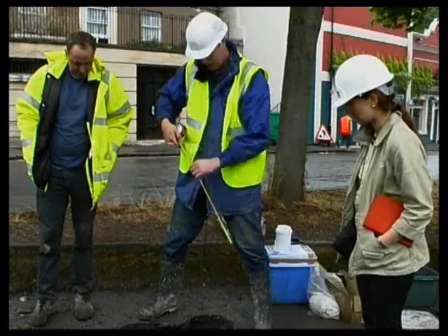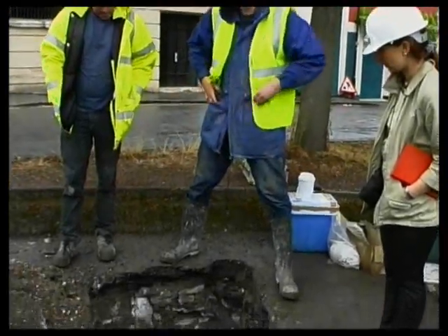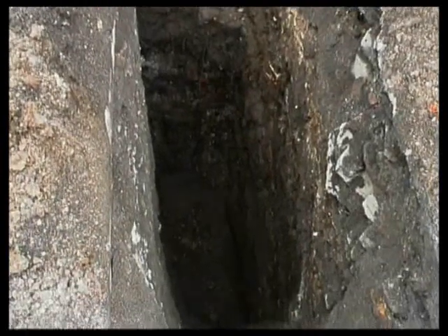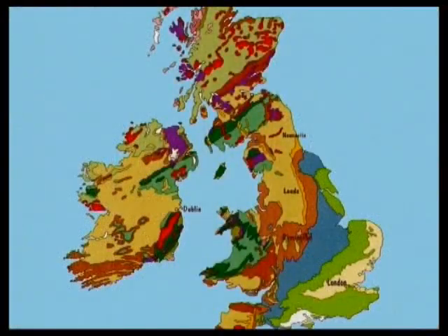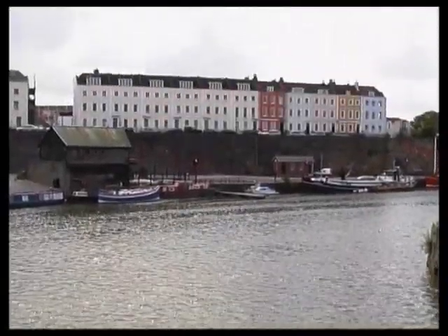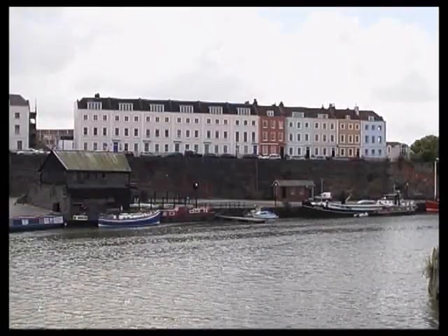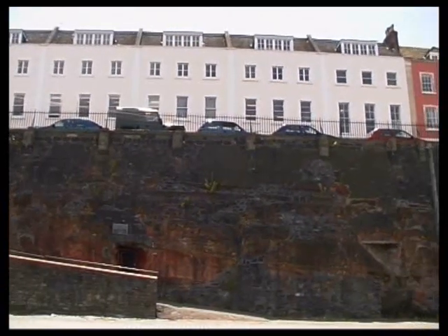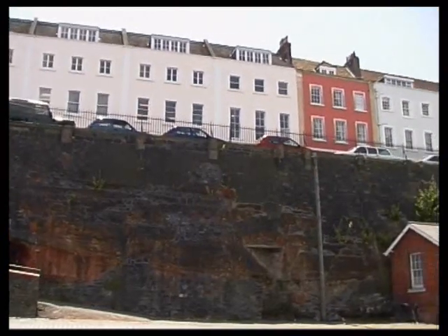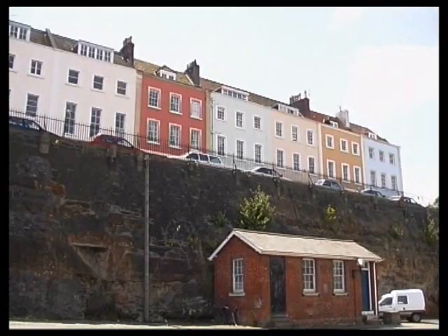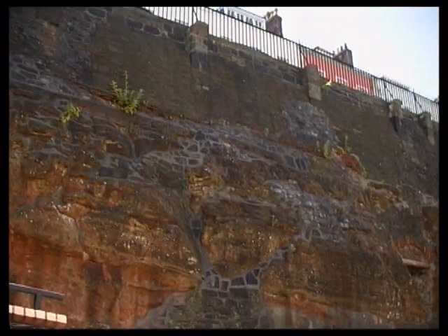In the UK, there are a number of different types of subsoil, each with its own characteristics. Their bearing capacity, in other words, the loads they can safely carry, will vary. Stable solid rock has a very high bearing capacity and can easily carry the loads of housing. Excavation can be difficult, but in most cases a concrete foundation is not necessary. The rock only has to be levelled, ready for the bricklayers.